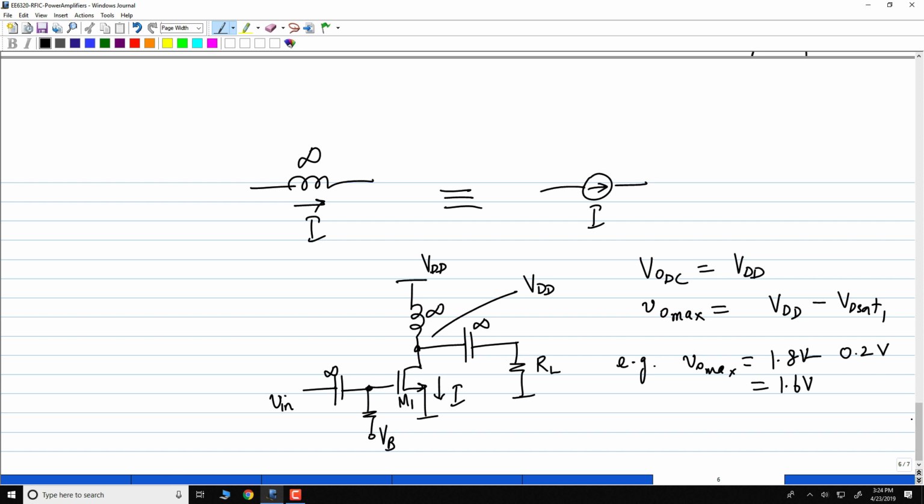So how much power will you get? 16 times more power. Okay, what is 16 into 2.5? 40, right? So you'll get about 40 milliwatts out of this, just blindly. You can see it's about an order of magnitude higher linearly. Okay, what is PSAT? It will be slightly higher because now VD sat you can push it into the linear region. So PSAT may be like a dB or 2 higher, not much more.